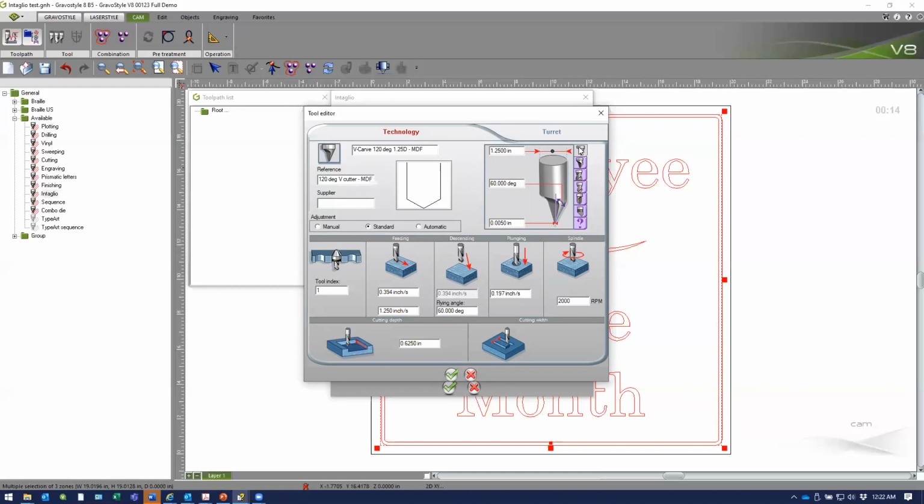So the first thing that I will do is select the contour of the cutter. So this cutter will have a sharp tip. There are other selections for a rounded tip, like a ball nose end mill. This one would be, for instance, for a 90-degree end mill. Others for drill bits, etc. So you have the ability to pick the profile that best suits your cutter. So here, the reference appears to be the diameter of the shaft of the cutter or the cutter shank, but indeed, really what we want to enter into this field is the width of the cut. So the width of that cutting head, and in this case, it was 1.25 inches.